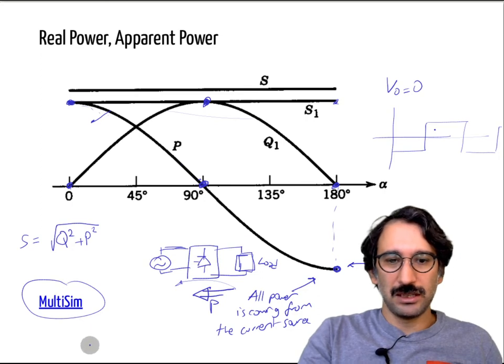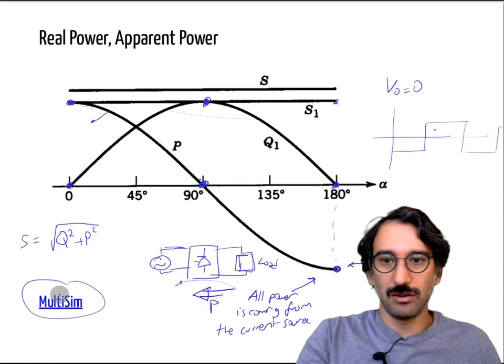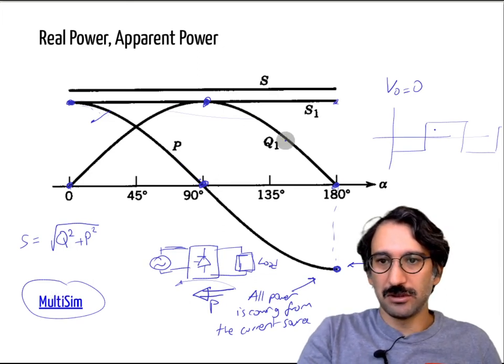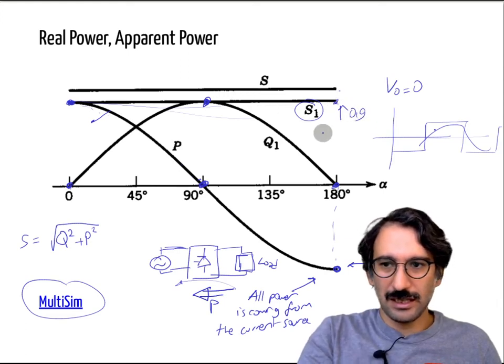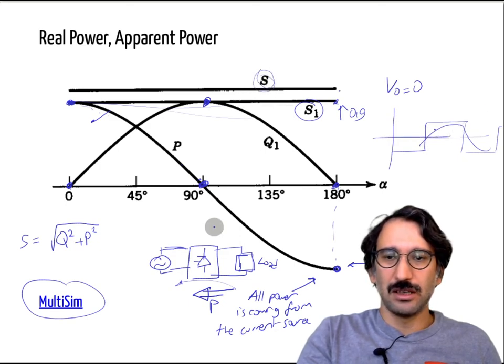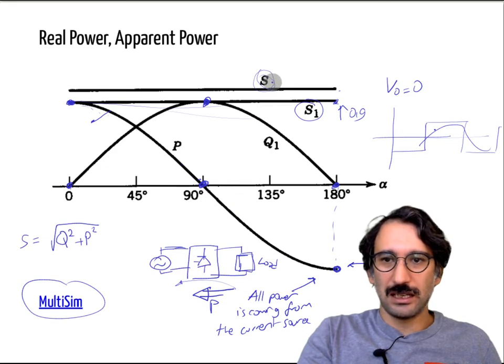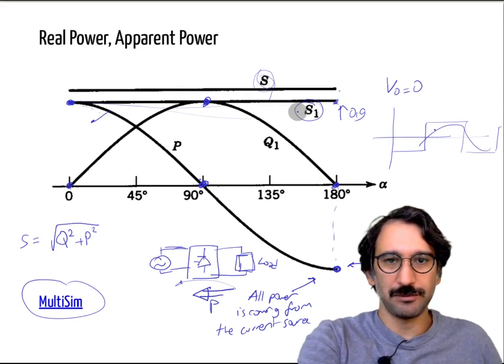And actually, please have a look at that simulation file. You can run it in your own browsers, and you can check how the voltage and current waveform changes. And that line, actually, it's all calculated with respect to the fundamental components. And this is 0.9, this is the 1, and you have the third harmonic, fifth harmonic, other harmonics. And if you calculate all those things, your real apparent power is slightly larger than the first component of that apparent power. Okay, cool.